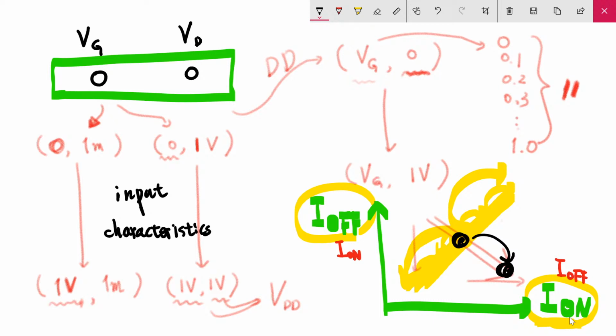For example, mobility engineering can introduce a certain knob to increase performance. Certainly when we have a higher mobility for our system, electron mobility and hole mobility, now without changing the off current much, we can increase the on current. Once we move in this way, then by changing our threshold voltage a little, we can live with this line.